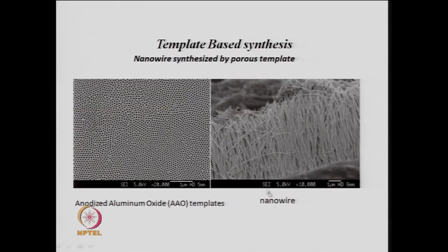And this is an example of some metallic nanowires as shown here, and the scale here is 1 micron. So, if the scale is 1 micron, then these nanowires are quite thin, as you see, compared to 1 micron. So, they may be around 10-20 nanometers in diameter. By this method, depending on how big your template is, you can grow very large scale nanowires using the electrochemical deposition with porous electrodes.